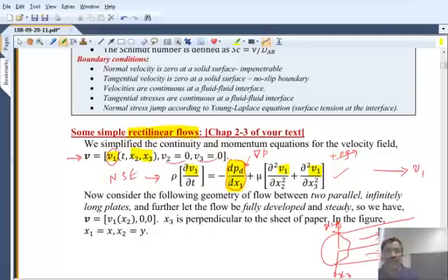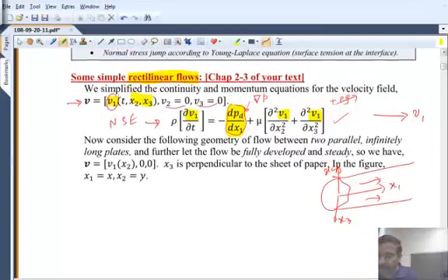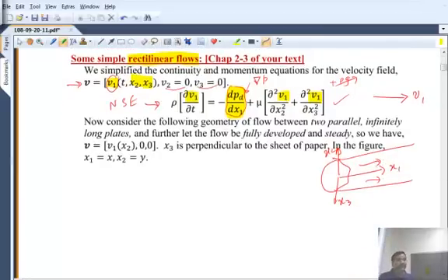So dp/dx1 is the dynamic pressure head that is developed by a pump, that is known, that is given, that drives the flow. That equation still is a partial differential equation, but let me ask you, is it a linear or a nonlinear partial differential equation? In this one, dp/dx is given. We're going to take that as a known quantity, but v1 is the unknown.